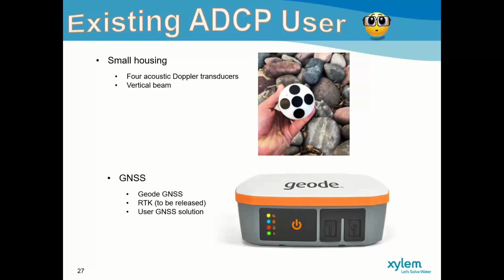It can also, on its own, access network RTK. But for the fact that Australia and New Zealand don't receive SBAS signals, the best you will get out of the Geode is using the VTG data string. GGA will still not be sufficient accuracy because we don't have external corrections.